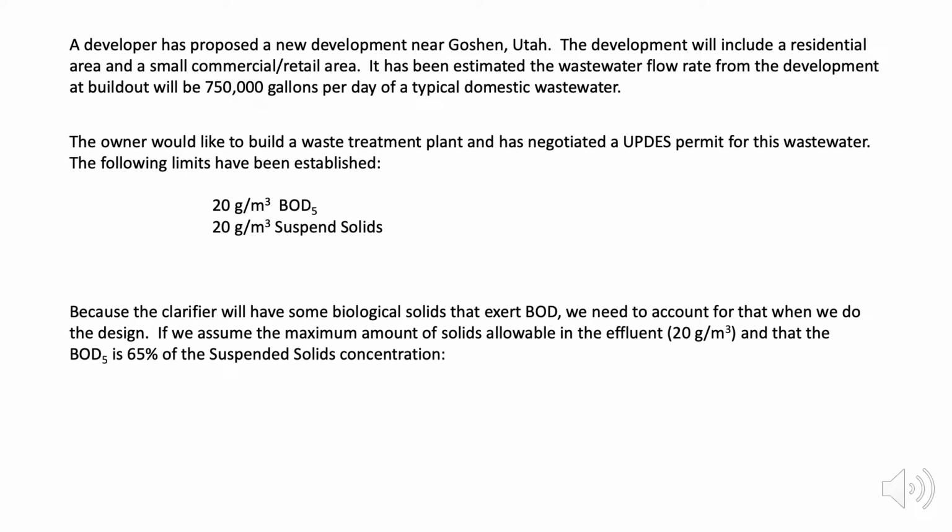So let's assume that they have 20 grams per cubic meter coming from that clarifier, and that 65% of those suspended solids will exert BOD. So basically the BOD exerted by the solids is 65% of the solids concentration. So now the design BOD concentration that we need to use is the BOD5 that's allowable, which is stated above as 20 grams per cubic meter, and then we need to subtract off the BOD that comes from the suspended solids, so that's going to be 0.65 times 20.